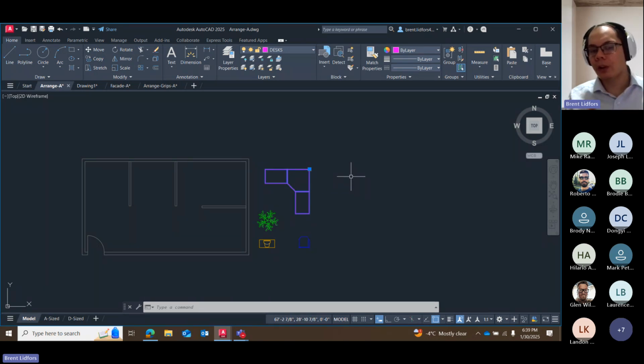Where we have corners on objects that are going to meet up, it's generally an endpoint to endpoint snap. So this guides you through it, telling you exactly what snap to use. But in the actual graded assignments, I'm not going to tell you explicitly what tools to use at times. So it might be up to you to figure out which snaps should be active or which tools to use.